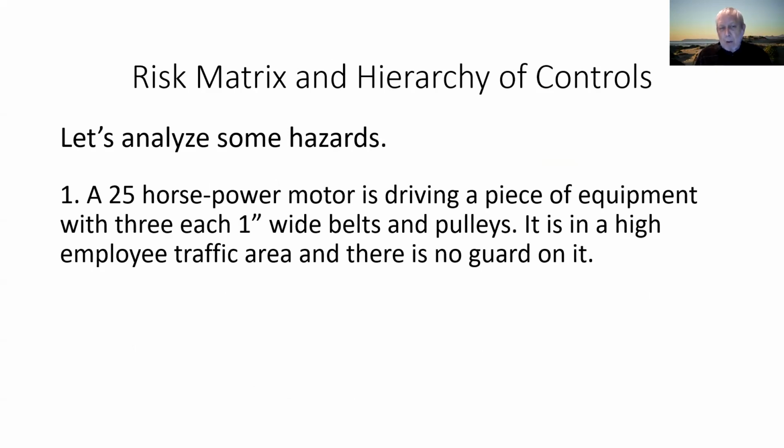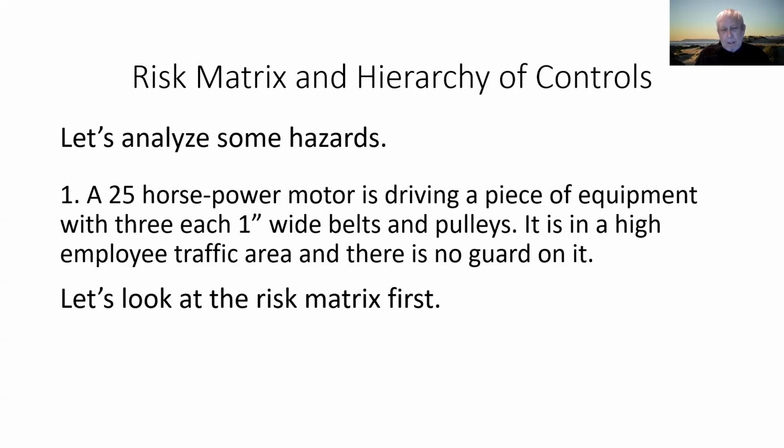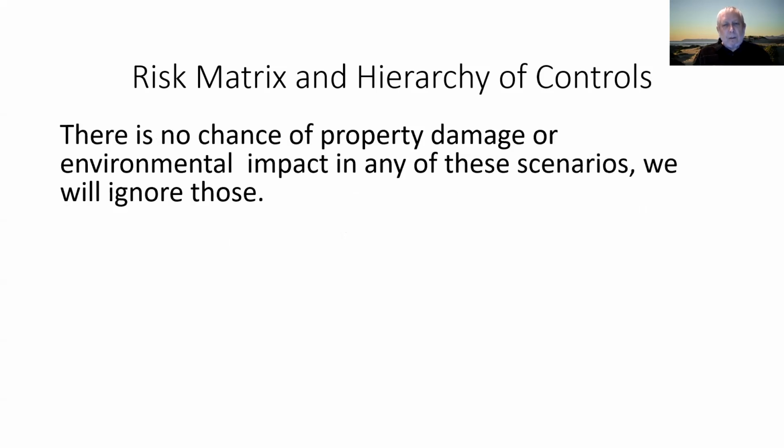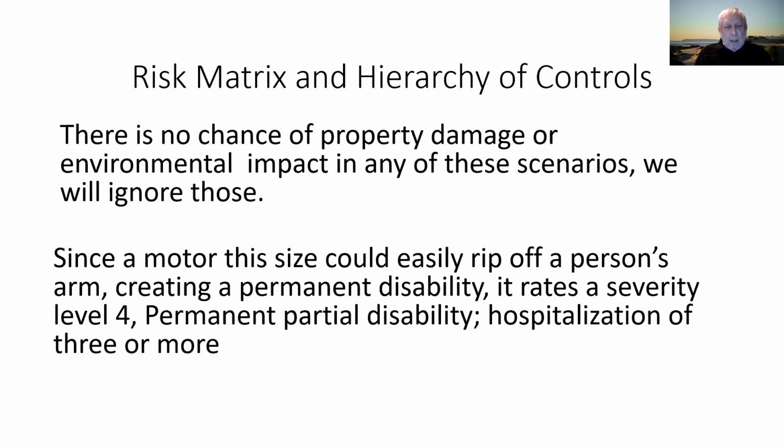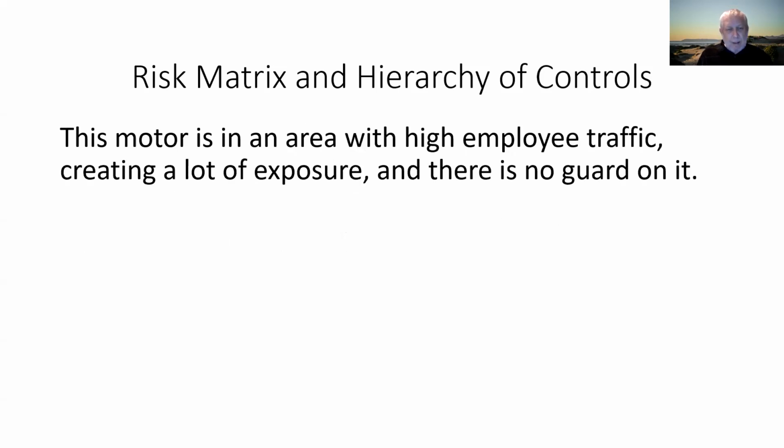Okay, a 25 horsepower motor with belts like that is going to be pretty powerful. There's no chance of property damage or environmental impact in any of these scenarios, so we're just going to ignore those for this exercise. Since a motor this size can easily rip off a person's arm, creating a permanent disability, it rates a severity level 4, permanent partial disability, hospitalization of 3 or more. Oh, that's on the old one.